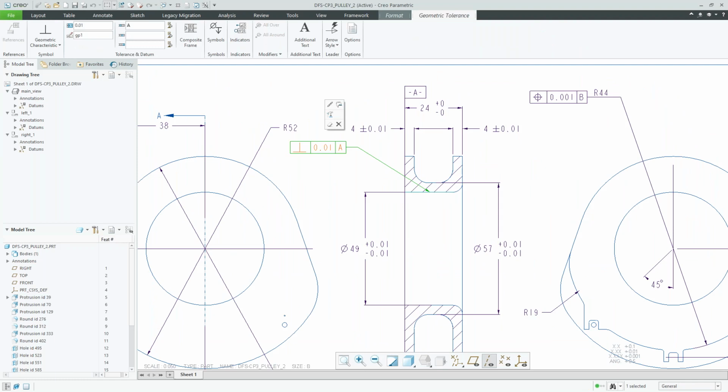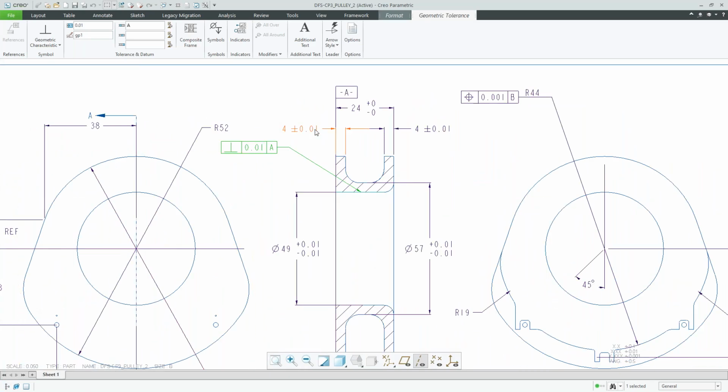And when you launch the, in our case, the geometric tolerance tab, after double clicking on this annotation here, you can see, and it helps a little bit if we push this guy out the way so we don't have a lot of distraction. You can see the primary area here shows the letter A in the black tint. That indicates that the datum feature symbol has not been defined in this case.